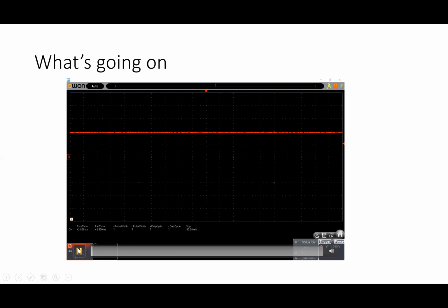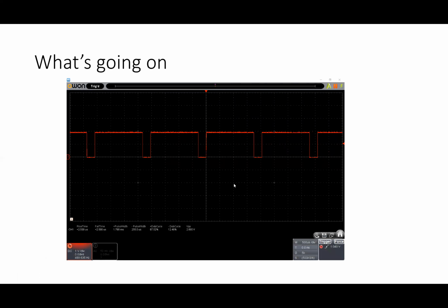By the way, 6 of the digital pins have little squiggles on them. That means they can be pulse width modulated. So here we go. We start up at 5 volts, and the signal is at plus 5 volts. Then as we turn the voltage down, you'll see that the voltage goes down for an amount of time controlled by the potentiometer until eventually it's all 0.